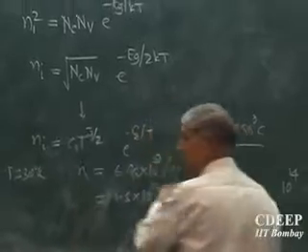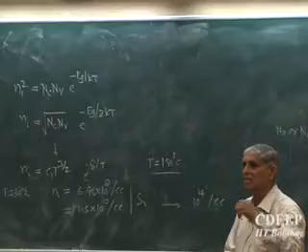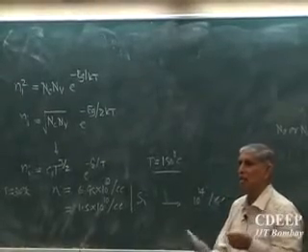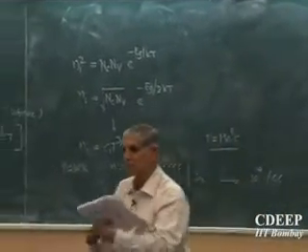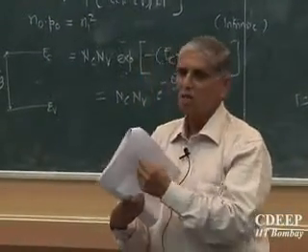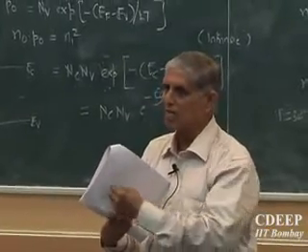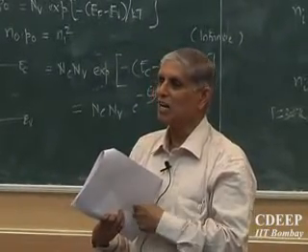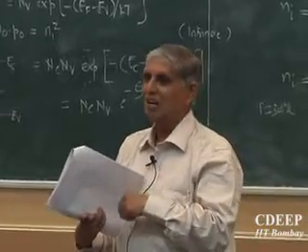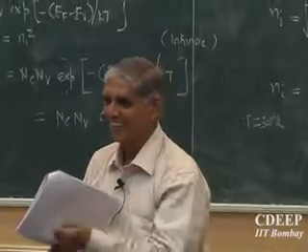This is an issue which I didn't have here, but since I saw these numbers, I thought we should know why we are worried so much about cooling. I suggest you research and check out how to cool using silicon substrates on which these circuits are made. Some circuit below, which is called MEMS, microelectromechanical systems, may create microchannels. And in those microchannels, we can have closed circuit liquid cooling.